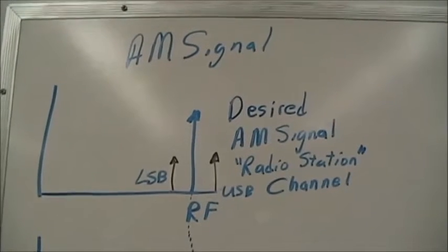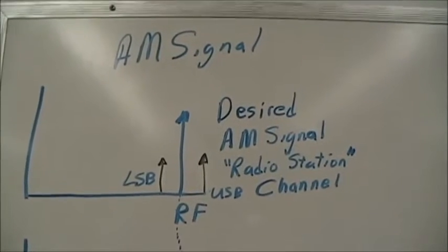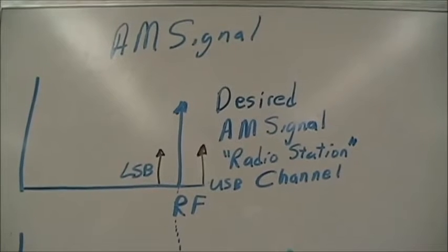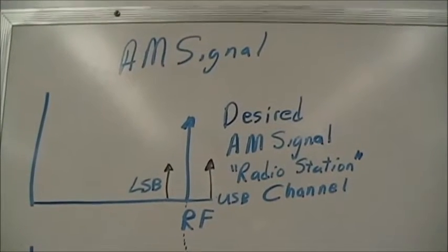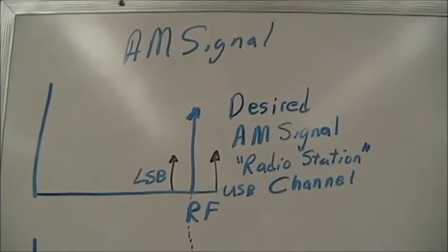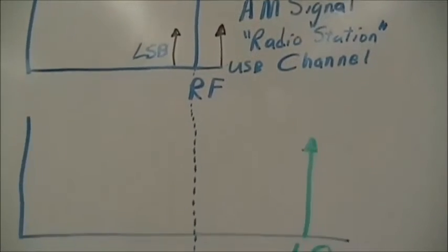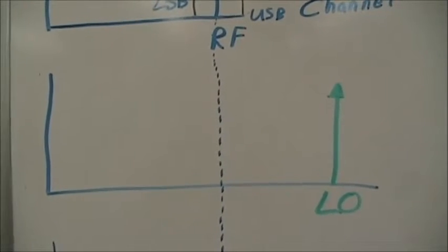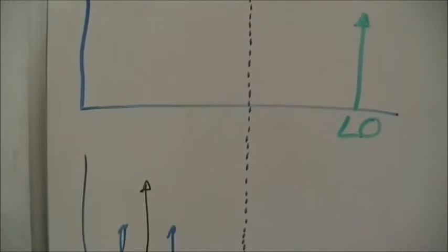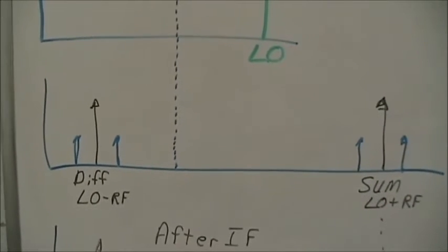That is not required, but that is typical. When the RF signal is modulated, we of course create a lower and upper sideband. In this case, we're assuming sinusoidal modulation of the carrier. The LO is simply still an oscillator at a given frequency. But now the two mixed signals are different.